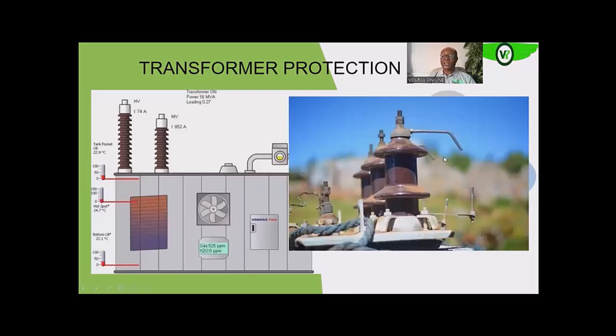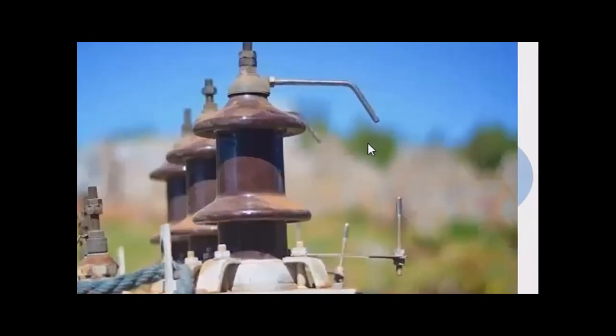And then once the dielectric strength of the air is broken down, you see that charges, or current, will be forced through the other part of the arcing horn to ground. So once that happens, that excessive voltage spike will not go into the transformer winding. Instead, it will be clipped to ground. So that is how the arcing horn works.